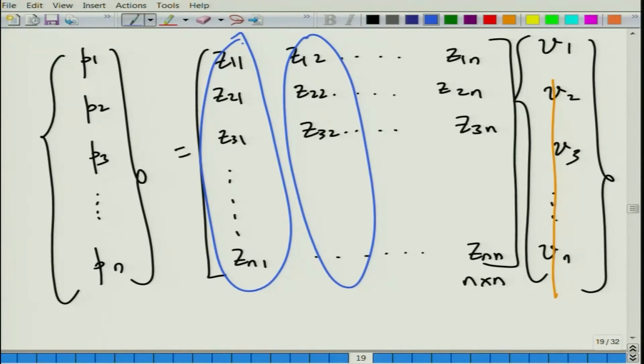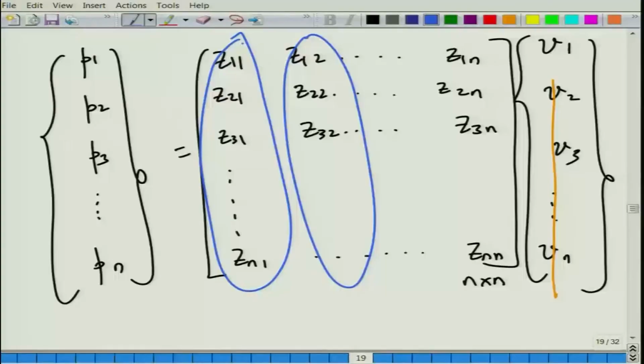It is very similar, P1 by V1 or P2 by V1. These are very similar to your transfer functions, acoustic transfer functions, which a lot of authors prefer to call them. In a sense, impedance matrix parameters or acoustic transfer functions are one and the same. They have been used interchangeably in many papers, but they are one and the same. And using these transfer functions or the impedance matrix parameters, one can also obtain the transfer matrix parameters or the 4 pole parameters.